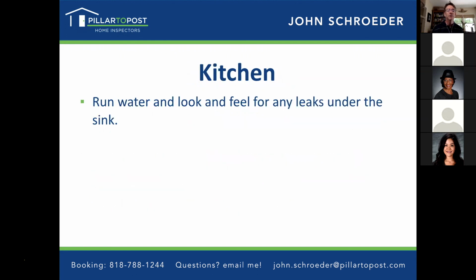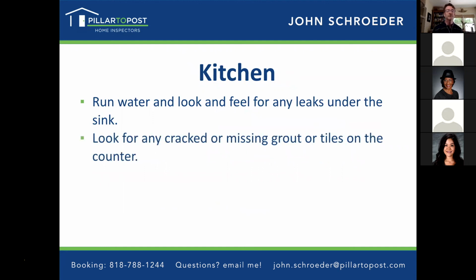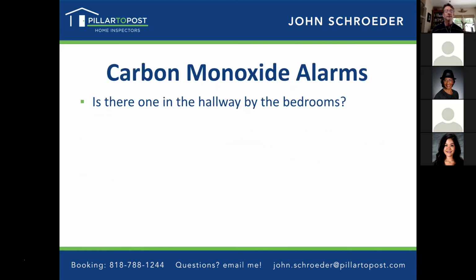In the kitchen, run water and look and feel for any leaks under that sink, of course. Look for any cracked or missing grout or tiles on the counter. Confirm all appliances operate. Check for carbon monoxide alarms.